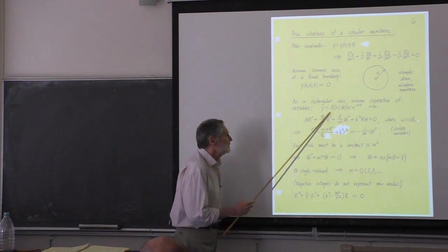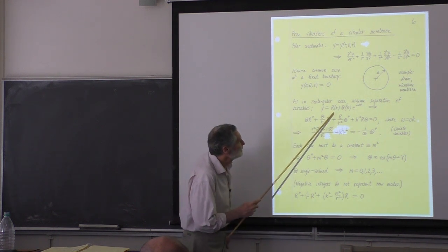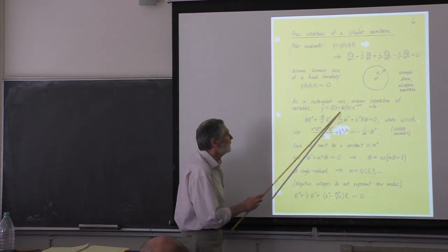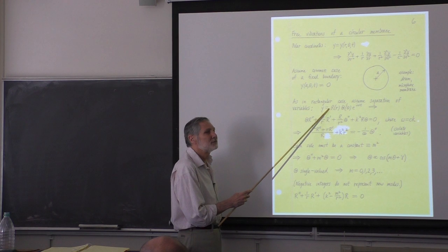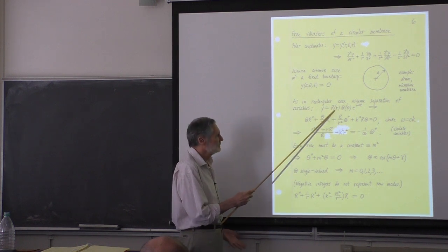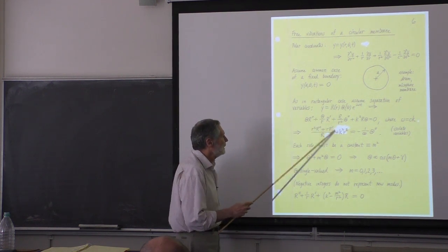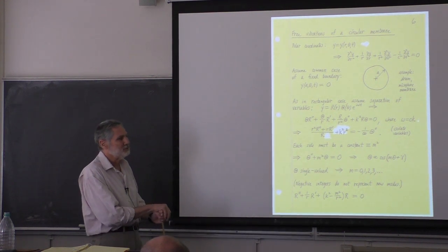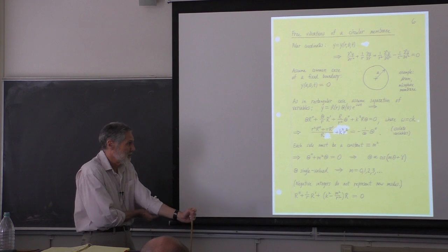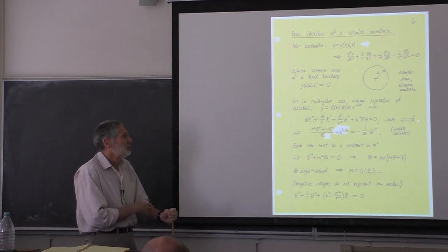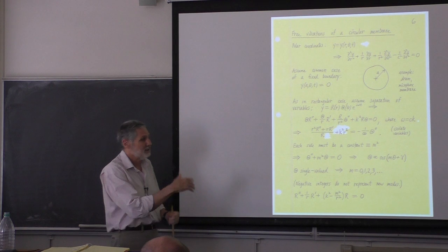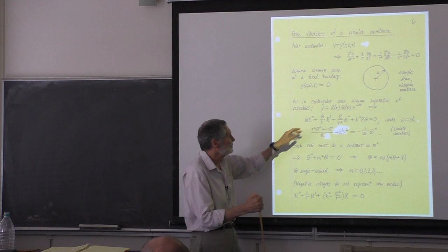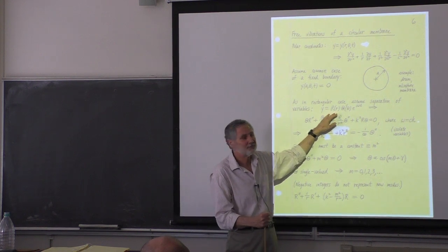So the procedure here is the same as before. We assume a separable solution. So here's our time dependence. We're looking for normal modes. The R and theta, we assume it's a product, we assume the separability here. And again, that's justified at the end because the functions that we're going to get are known to be complete. They are known to describe any possible excitation, in this case, any possible excitation of the membrane. It's going to be described by a superposition of the solutions we get.